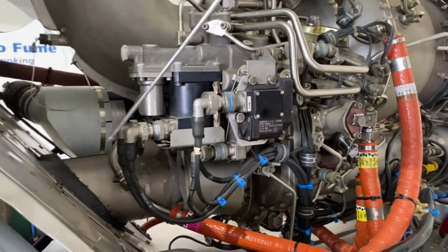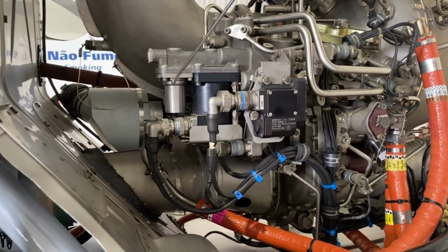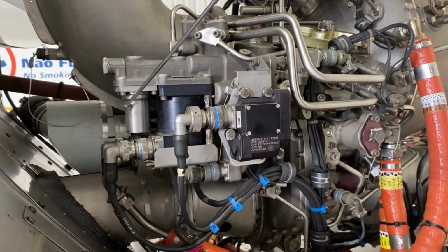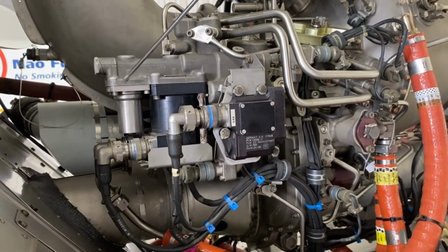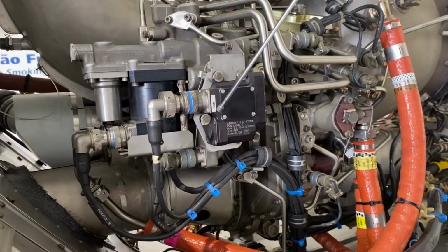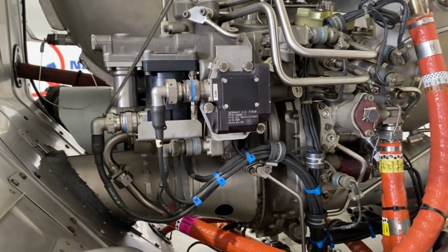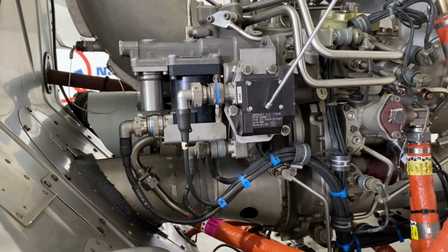I'll show the cargo compartment, where it is located. It controls the FADEC computer, the ECU, and it needs to know if the needle is in position, so it has the resolver transmitter. Here on the body, we have a small actuator, which is the manual override actuator. In case both channels fail, the manual override comes into operation.